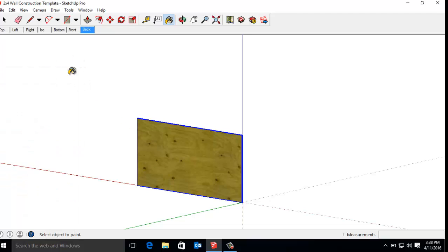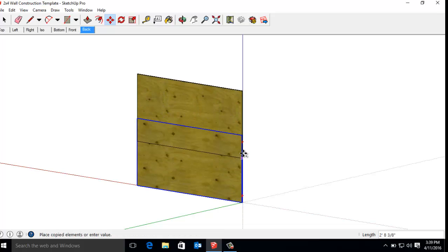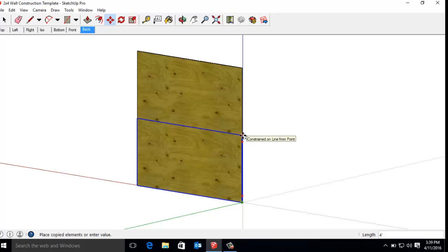Now the good thing is we don't have to draw 2 of these. So I'm going to first select it, but I already have it selected, so that's black arrow tool to select. And I'm going to grab the mover tool, and I'm going to take this endpoint. Now if I grab an endpoint, it'll move it and it snaps to the lines like we want it. But I want to copy it. So when I click, if I just hit the control key once, it copies it. And then you can see it's going to snap since I'm grabbing that endpoint. And then I click so it sticks.